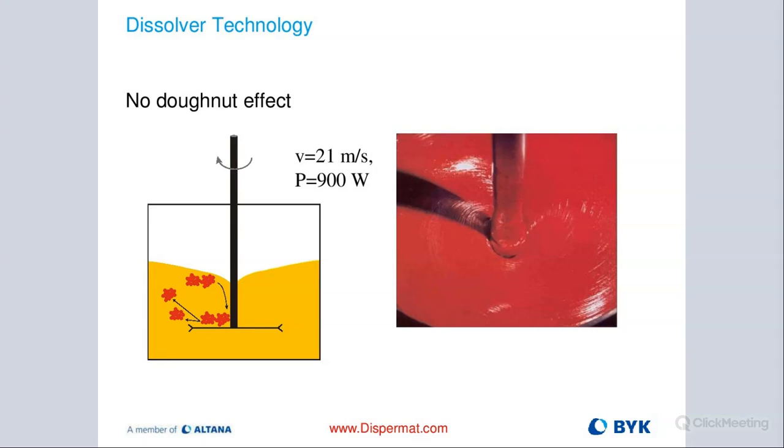So you could maybe modify your formula, but not really need it. What I would do in this case, I would maybe change the blade diameter to make it definitely larger to get the product moving, right? If it's very thick, a lot of times it tends to sit around the edges of the container and so on. You may want to use a larger blade to get the product moving. And then what also would be helpful here is maybe get a scraper system that keeps the container walls nicely scraped, with what we offer also. So that's a good system for a wall scraper for sure.